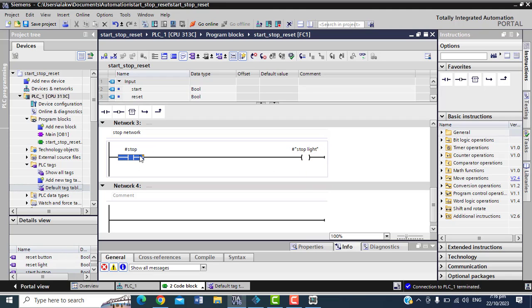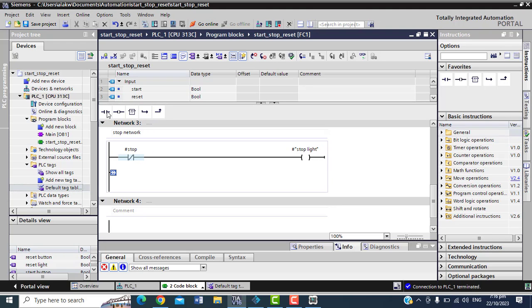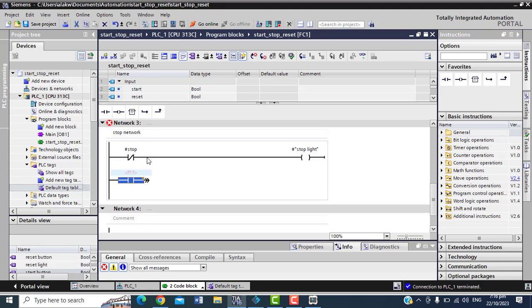So what I will do is change this one to normally closed, right? So that as the signal comes here, it doesn't come through without me even pressing this thing. It will open up, so signal cannot come here. If I leave it, it will close and signal will come. So I hope you understand the check there. The next thing is I will just latch them, just like every other one I did before. I will latch them, and again this time with normally open.